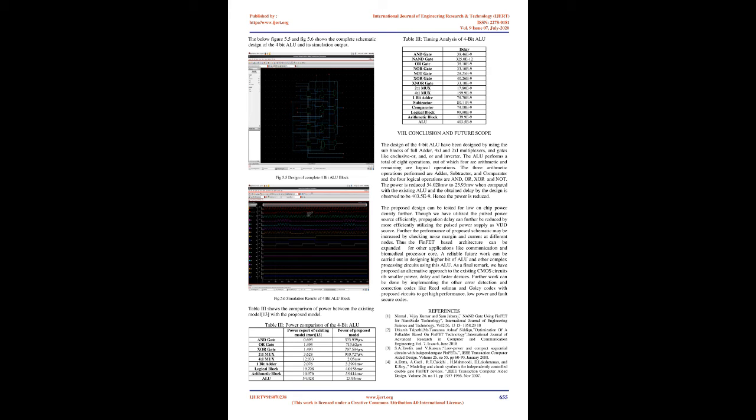4.5 Multiplexers. Multiplexers are used to combine data from different sources into one single data. The select lines help the mux to select a particular input to be switched as an output. In this study, 2:1 mux and 4:1 mux were designed and simulated. The 2:1 mux is designed with 2 inputs, 1 select line, and an output. A 4:1 mux is designed with 4 inputs, 2 select lines and an output.